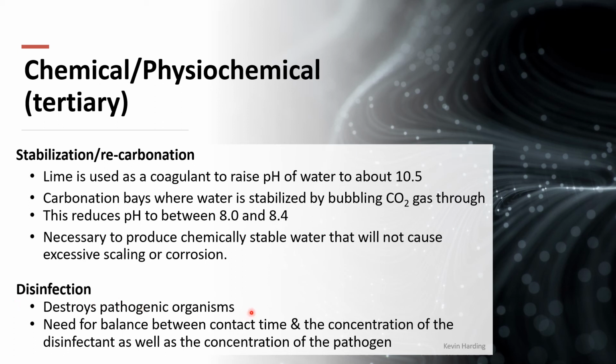So the water that you get right at the start of the municipal wastewater system might have various microorganisms that come in that are not wanted. We don't want to kill those microorganisms at the start of the process, because if we kill those bad bacteria, we're also going to kill the good bacteria that are going to be used in the aerobic and anaerobic digestion steps. So we're going to rather kill those pathogens right at the end before this water goes out, either into the river, the sea, or for other uses.